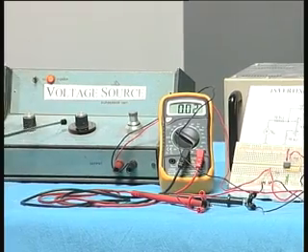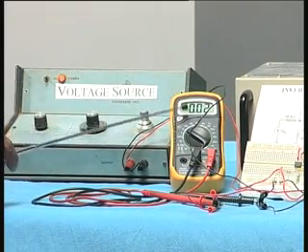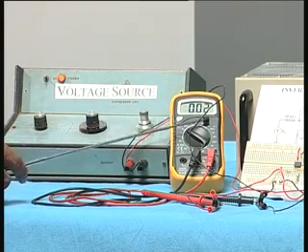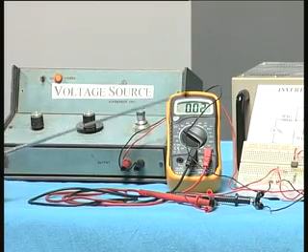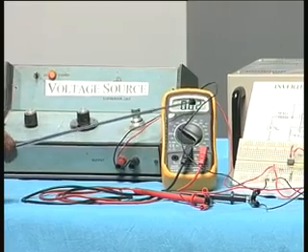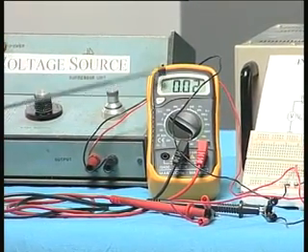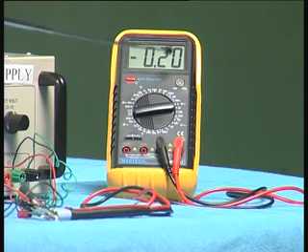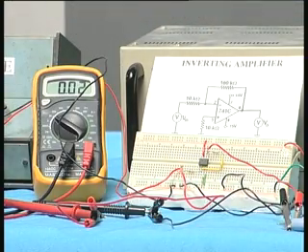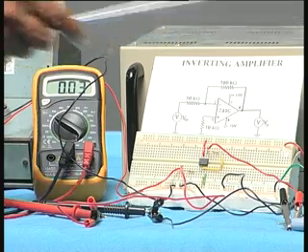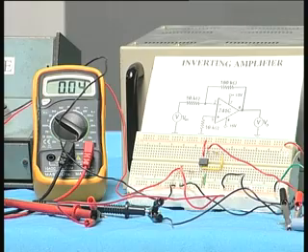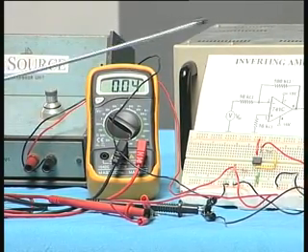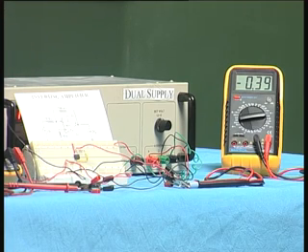So I have kept it here in 2 position, that means 20 millivolts I am applying. So the reading here is 0.02 volts, this is in volts range. 0.02 means 20 millivolts. If you multiply by 1000 you will get it in millivolts. So I have 20 millivolts multiplied by 10 should be 200 millivolts, and what I get in this power supply is 0.20 volts, that means 200 millivolts. If I put 0.3 here, 30 millivolts, you get 0.3 volts at the output correspondingly. If I make it 40 millivolts, you can see again it becomes 0.04 and the output voltage is 400 millivolt or 0.4 volts.